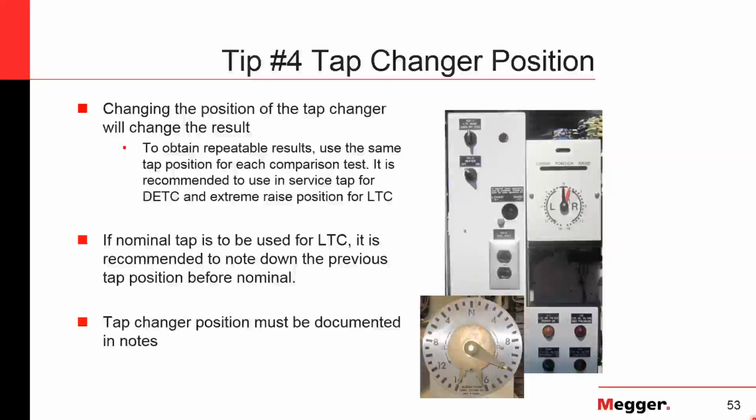Henning, I would say that we're looking at a circuit that is composed of resistive components, inductive components, and capacitive components. Every time we're talking about losses, we try to correlate everything to our I square R, especially when we're talking about thermal response. Even when we do a winding resistance test, we understand that the resistivity of the material, in this case copper or aluminum, will be affected by temperature. On my transformer, I may see results taken at 85 degrees C or 75 degrees C and reported. But in the field, you might be measuring at 20 degrees C.